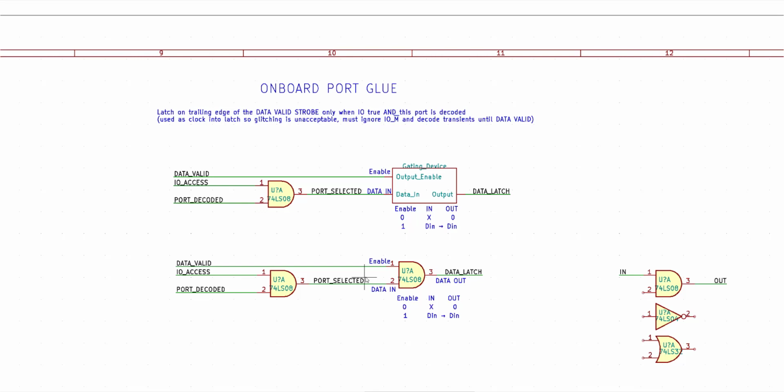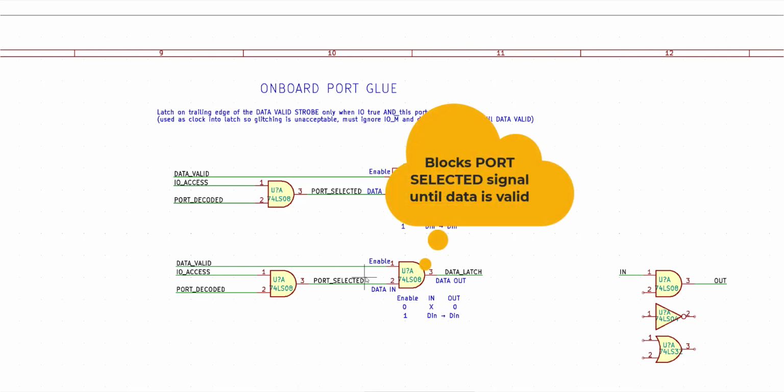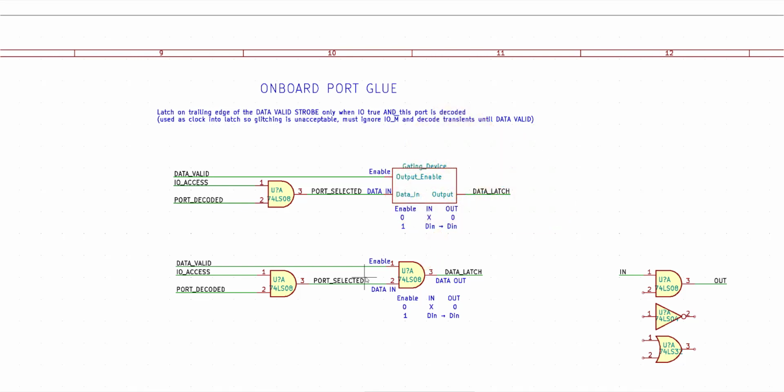And the superior signal may be an enable to an output or act as a gating device like this. It may be a clock to a latch, or as in the case of the exclusive OR, it may be defining the equality reference or serving as the invert control line. But look for the superior signal and conceptually what it's doing to that gate. Where this signal meets the others, make a notice to its function. If you don't already do something similar, I guarantee you that this technique will improve your schematic abilities. It'll make reading schematics faster. It'll help reduce hardware bugs.